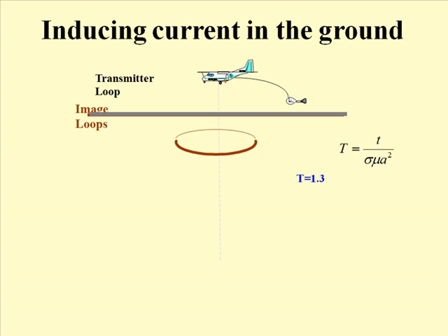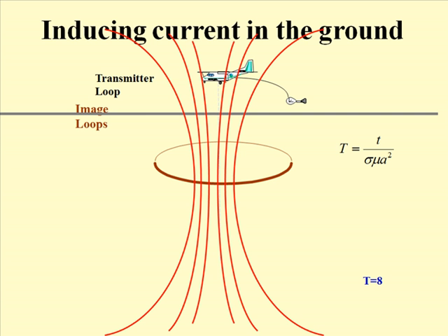This magnetic field here decays away as well because the currents that it is associated with are decaying away too because of resistive losses, and so this magnetic field is time varying as well. So you can see it flashes and an electric field will be induced circulating around it according to Faraday's law, and you see this on the next slide. Once again, notice that the electric field is now deeper and broader than the previous two examples.